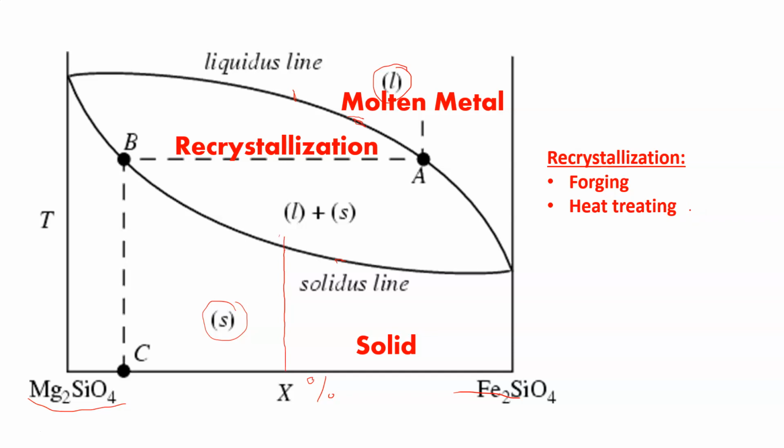Basically it's like hitting the reset button in a lot of cases for metal where the crystals have been deformed or damaged. Depending on how you cool the metal down, or what environment it's in, you can actually change some of the characteristics of the metal. So this recrystallization state, let's give it the formal definition. A process by which deformed grains are replaced by a new set of defect-free grains that nucleate and grow until the original grains have been entirely consumed.